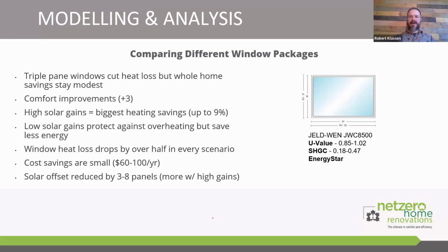One thing I'll chime in real quick is that part of the reason we skewed slightly towards more solar gain rather than less was the thinking that with the future solar array, when we do need to use energy for cooling, that happens to coincide with when it is most abundant. That helped justify leaning a little more towards higher rather than minimal solar gains. If we were in a climate where winters are typically overcast, we probably would have chosen that differently.